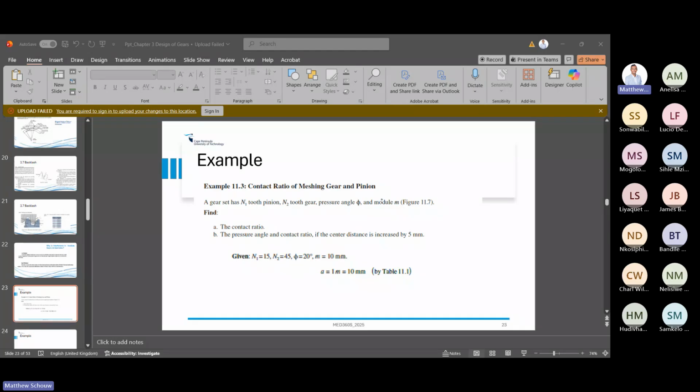You could have called it small d, big D, whatever. So obviously we need the diameter. From the diameter we get the base circle. From the base we have to add the addendum. C is our center distance. Our center distance is R1 plus R2, if you guys remember, or we have another way using the number of teeth as well. And then obviously P, just to recap, I'll come back to P.